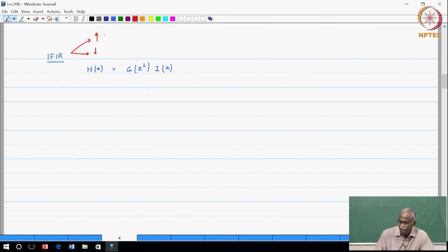Both of them require filters, and the IFIR technique is particularly advantageous if you have to have one of these. The key point to note is that this is where you get the sharp filters. This is what produces sharpness, but along with the sharpness it produces some unwanted images, and this is what removes the images.